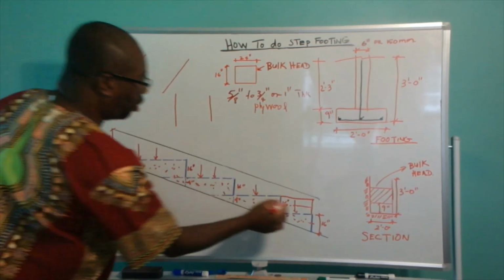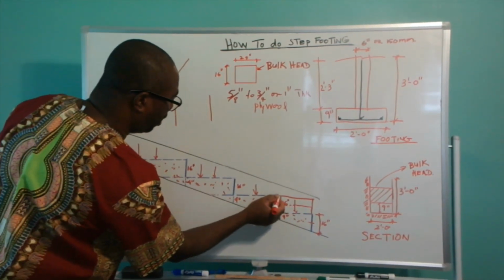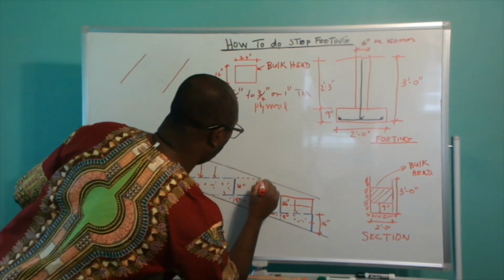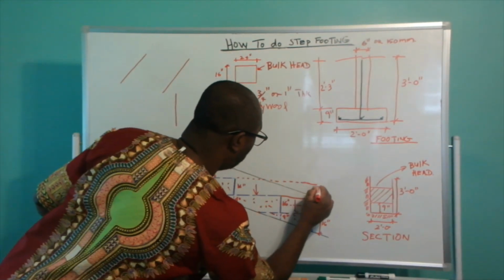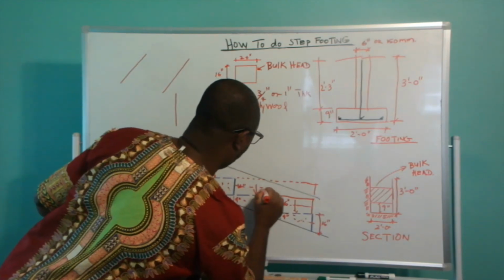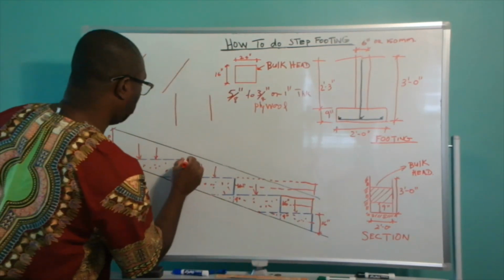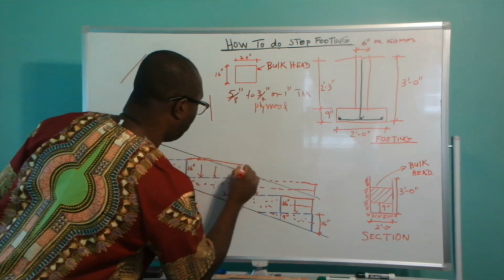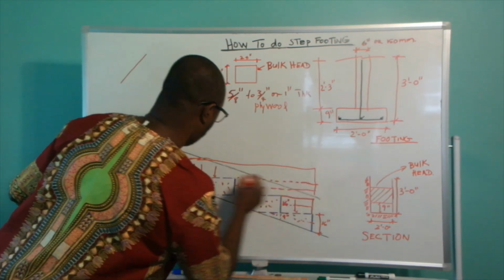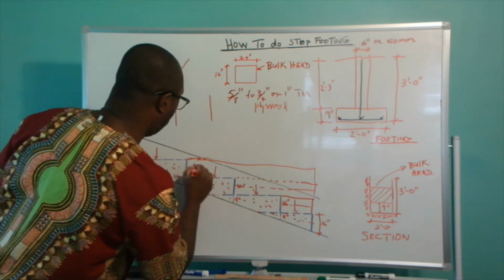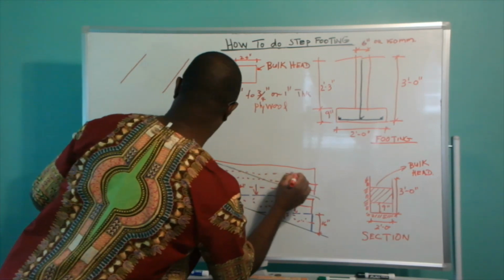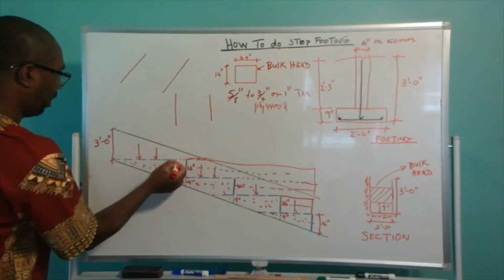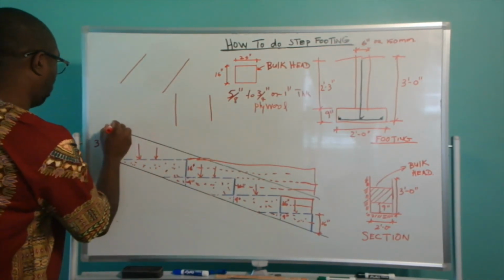And you want your wall to look something vertical like this. So from here to here is 16 inches. Then you're going to lay your blockwork again, 2 rows of block. And you notice that this block height is level with the top of the concrete here, and then you can continue